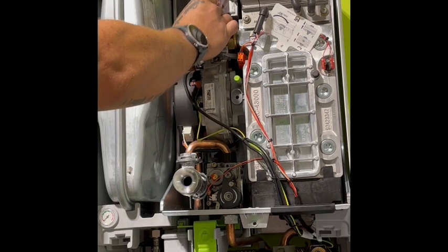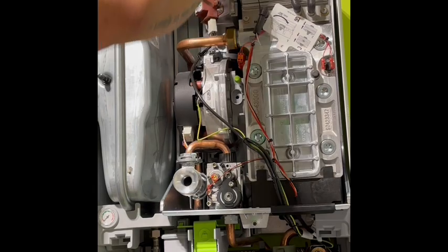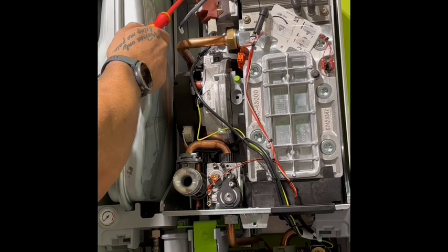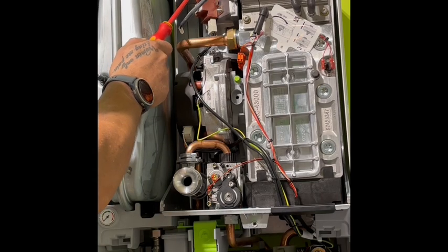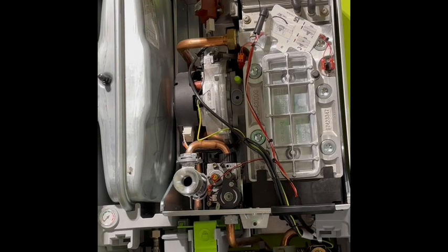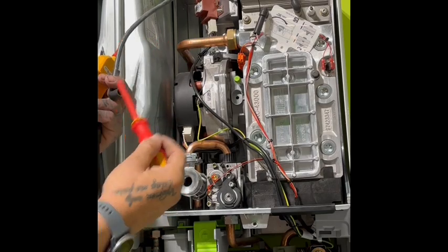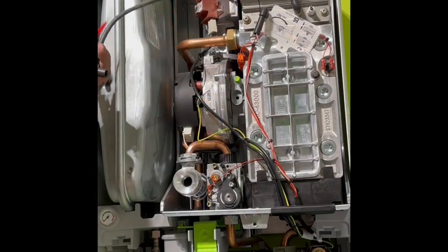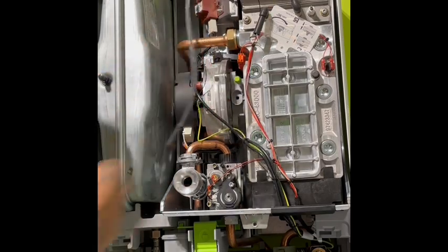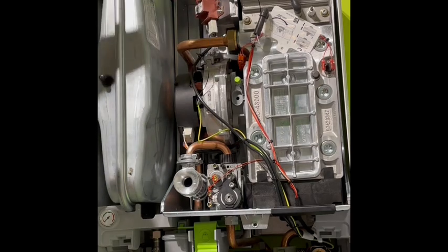It's then about proving that the spark generator actually works. Ways we can do that: we can pull that lead off there, put an electrically insulated screwdriver to it and see if it arcs from that terminal to the end of the screwdriver. We can also pull it off the actual spark electrode itself and do the same thing there. That will prove that our harness in between the electrode lead is okay. It's not uncommon for these to break down in certain positions and arc out somewhere. Make sure there's no damage on your leads anywhere.